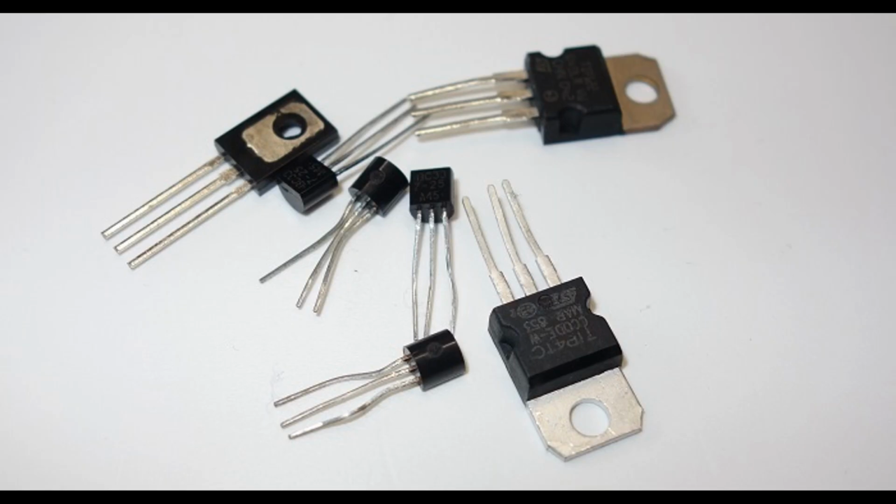A field effect transistor, FET, is a type of transistor that relies on an electric field to control the flow of current. Unlike a bipolar junction transistor, BJT, that uses both electrons and holes for conduction, FETs are voltage-controlled devices and primarily use either majority carriers, electrons or holes, for conduction. There are 2 main types of FETs. Junction field effect transistor, JFET.